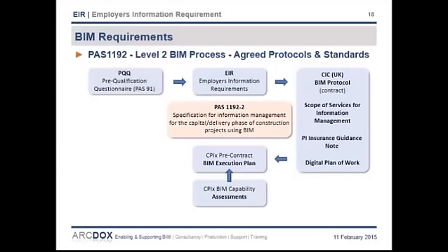Then anybody who's tendering for either design or construction services needs to be able to demonstrate that they have understood the information requirements by producing a pre-contract BIM execution plan complete with BIM capability assessments. And this is their response to the EIR. And to help the client assess these pre-contract BIPs, we would highly recommend that a template is provided for designers and contractors to complete. Otherwise, you'll get a wide variety of responses ranging from a single paragraph to a 50-page document, which will make it very difficult to compare and assess.